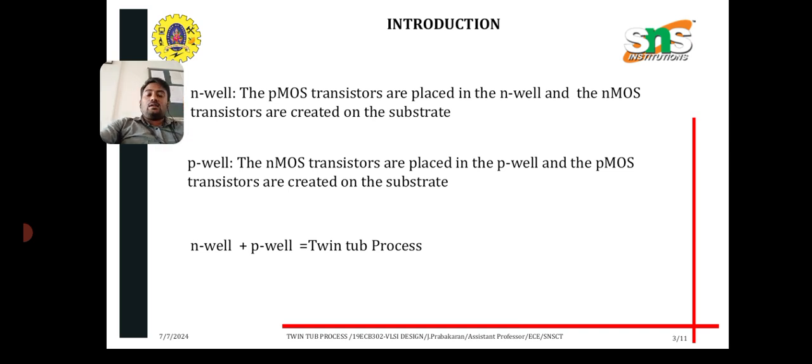And another one is photoresist removal, oxidation and P-well masking, and another step is oxide etching for P-well and P-well formation, and photoresist and oxide removal, field oxide formation, and channel stop implantation, and gate oxide formation, polysilicon deposition, gate patterning, and LDD implantation.